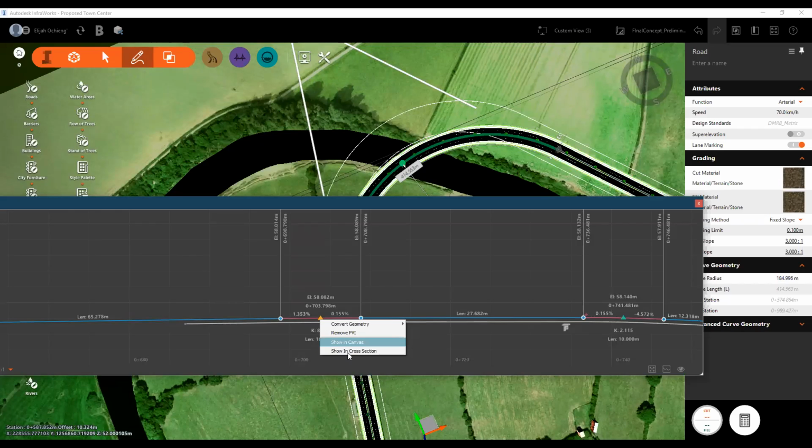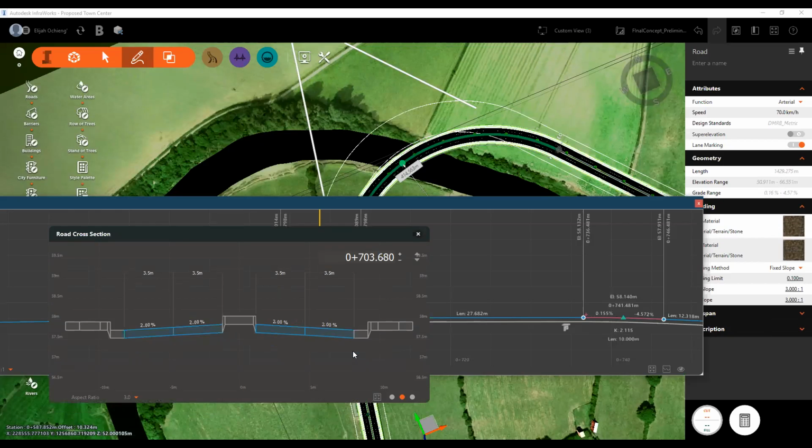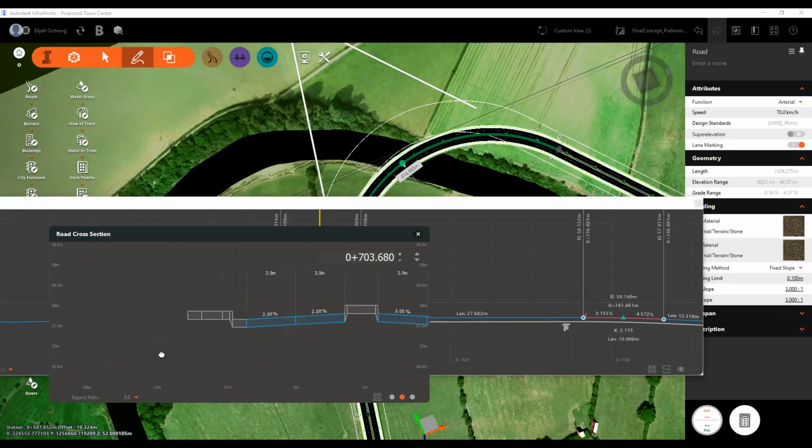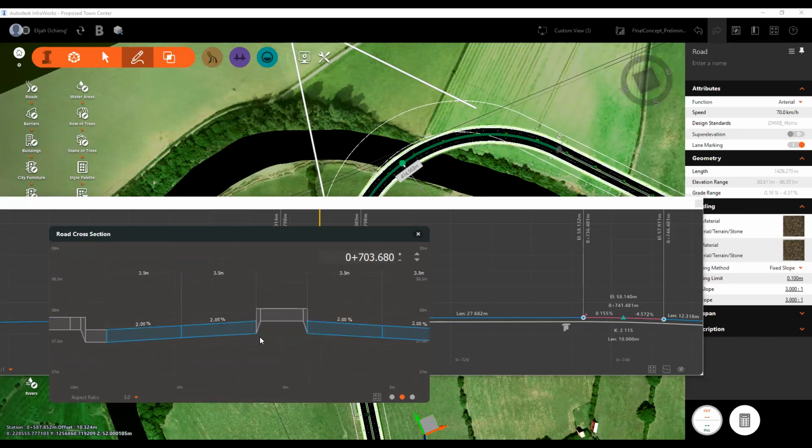You can alternatively choose to show each of those points on the cross section to get an understanding of the various sectional slopes you have used, or the camber, and whether you have correctly applied the superelevation, that's the rate of change from one point on the left or right hand side of the road towards the center, to enable vehicles to counteract the effect of centrifugal force.